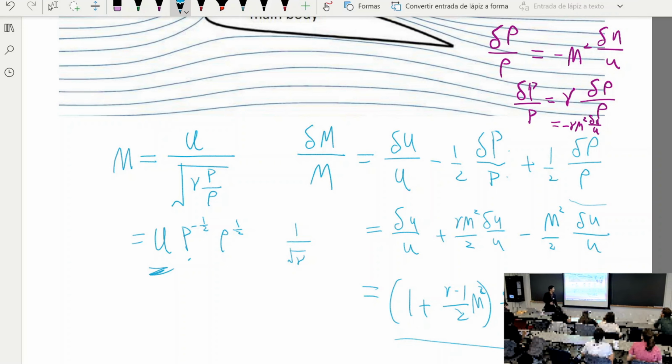So when Mach number is close to 0, a 1% increase in velocity means a 1% increase in Mach number. There is no surprise on that, right? Because speed of sound is pretty much constant. As you accelerate, density barely changes, pressure barely changes, therefore temperature barely changes, therefore speed of sound barely changes, and the 1% increase is a 1% increase. But at higher Mach number, the higher the Mach number is, the bigger change in Mach number is driven by the same increase in velocity, right?